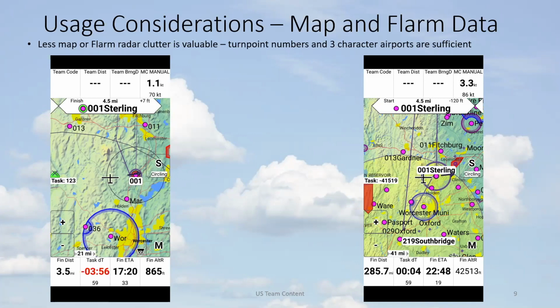And the reason I prefer the one on the left is you get some information about the terrain. So when you're soaring, having a good idea of whether it's a wet valley or some high ground is particularly useful when picking your route. You want to go over the high ground with sunny facing slopes, and you're going to get more thermals off that, and they're going to be stronger than the stuff that's moist or in the middle of a wet river valley.